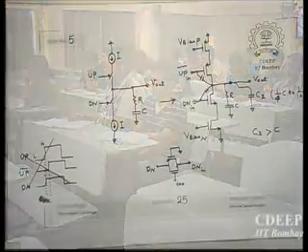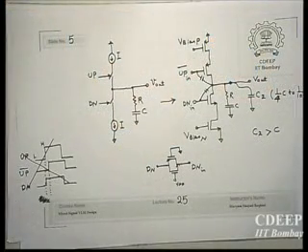Another problem is you may have a mismatch between source and sink current. That is one of the big issues. Because one is NMOS and one is PMOS, the output impedance of these two is not the same. And even if your output voltage level changes, because output impedance is not always infinite, you will get some mismatch.